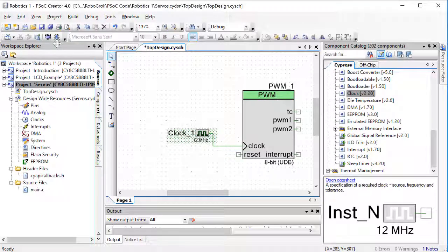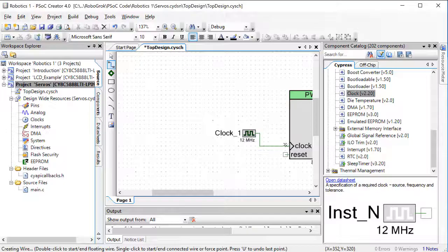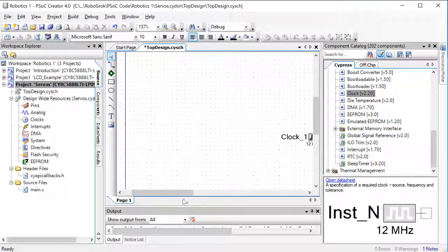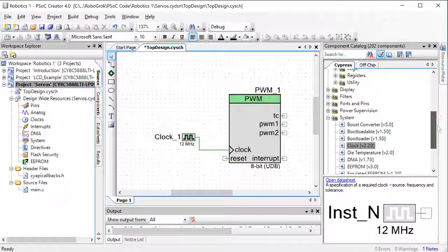If you now drag the clock away, you'll see that they're connected by a wire. If these 2 things are not connected by a wire, you can make them connected by using the wire tool. You can click on 2 different inputs or outputs with the wire tool to make them connected with the wire.